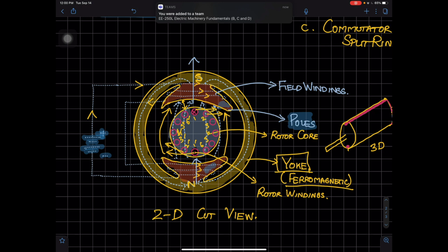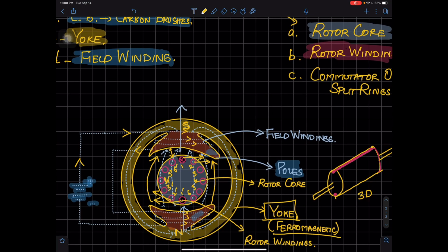So now the torque which is going to be produced, and we all know torque is equal to R cross F, where R is the moment arm and torque is the total torque produced over there. So now this time when there are 6 loops, we are going to have those 12 forces produced. Maybe they are having a little different force because of the angle over there, because I've told you F is equal to IL cross B. So now when this force is going to be added up, your total force of this whole motor is going to be more as compared to a single loop over there.